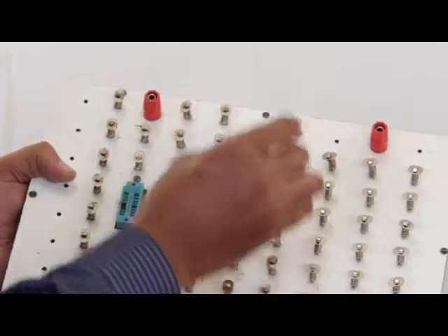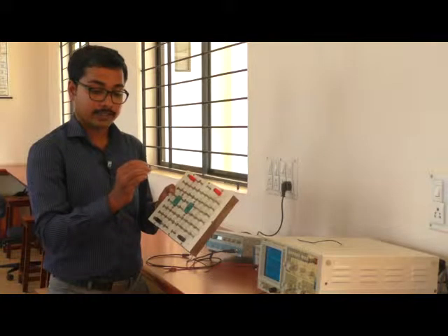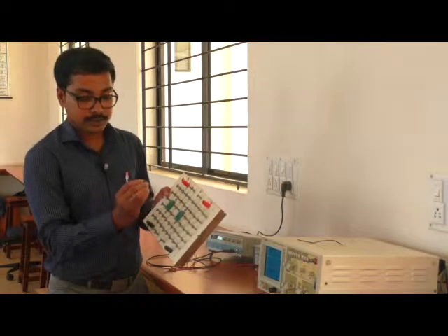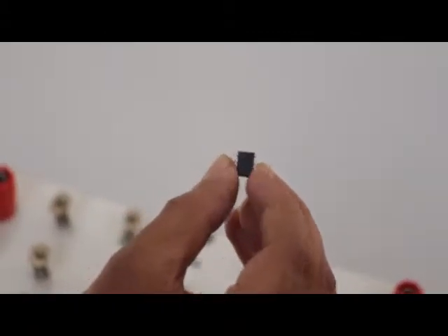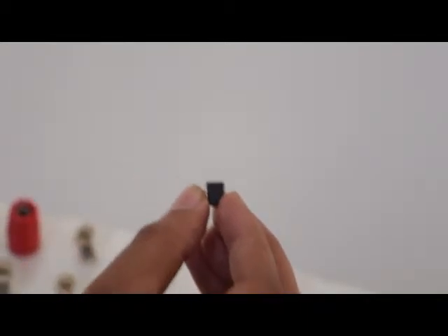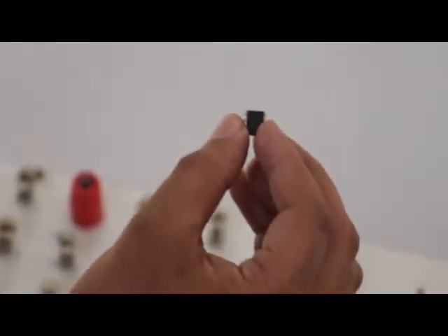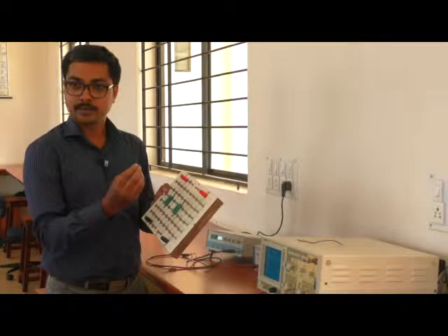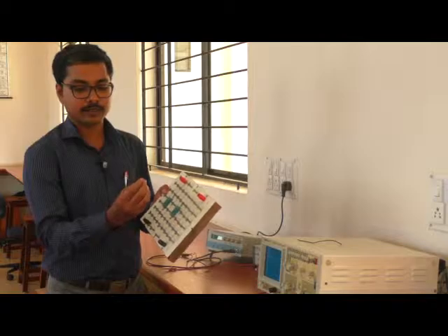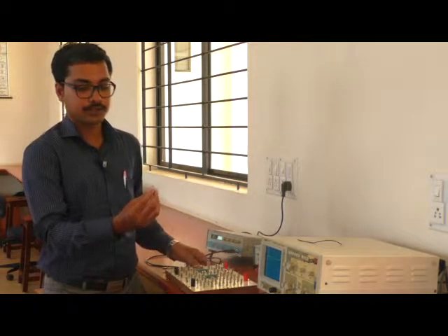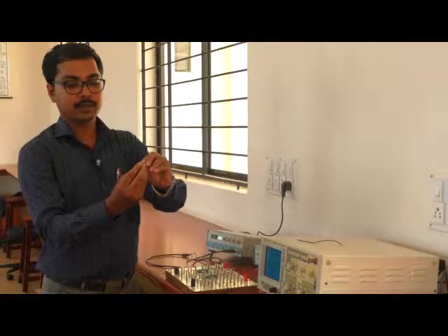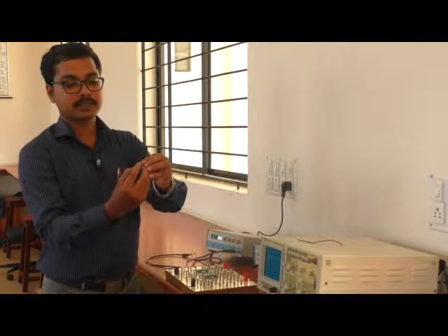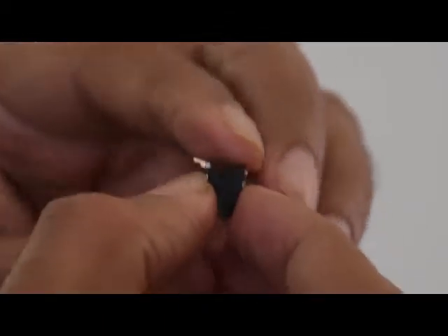I'm mounting the IC. How to mount the IC is very important here. The IC has 8 pins. From which side do we have to count the pin numbers? Here we have one particular dot, called a notch. Every IC has its own type of notch. That notch says that from this point we have to start taking the IC pin numbers, that is from the left, from this part. See, I'll show you. This is pin number 1, then 2, 3 and 4, 5, 6, 7, 8. That is how the IC numbering is counted here.